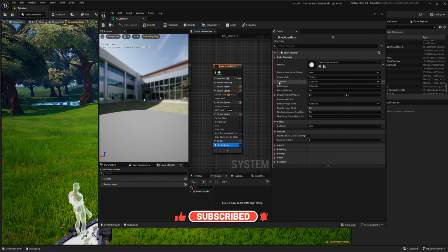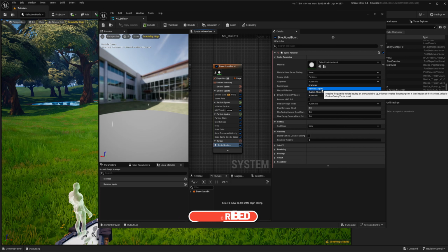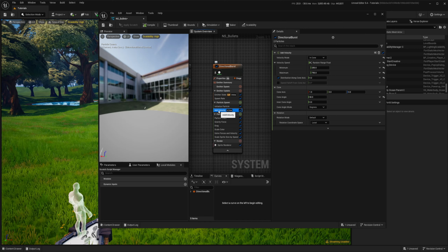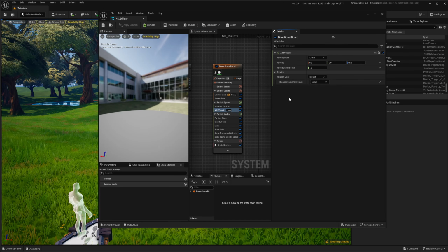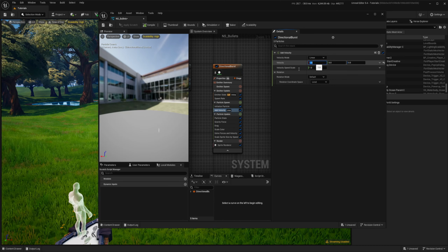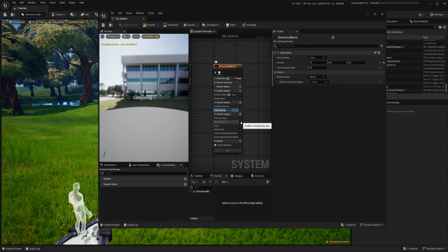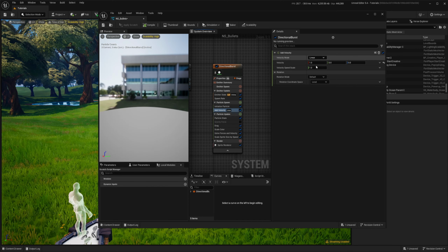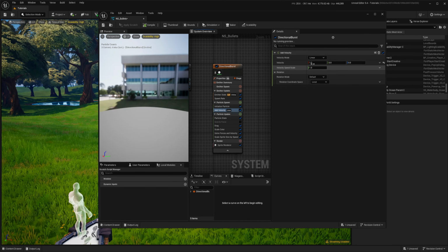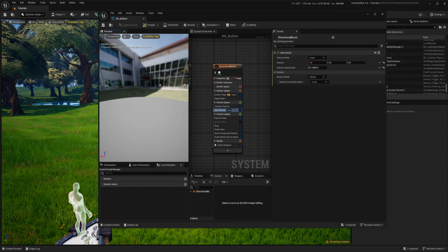In the sprite renderer, here in alignment, we can choose velocity aligned. Now they are properly aligned. In add velocity, I will choose linear, just like that, but instead of Z, so it goes up or down, velocity is 0, and I will pick X, which is forward. I will disable gravity because we don't want gravity for now. So we have X velocity, and this is a speed scale. So it will basically multiply these two parameters. So if I put, let's say, like that, see, it's shooting.